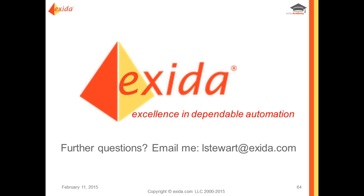Next, if you want to improve your PFD average, if you think back to the calculation, what were the main pieces of information in that calculation? You can decrease your proof test interval. You can decrease your mission time. You can change your architecture to 1 out of 2 or 2 out of 3, or you can revise your proof test coverage. A few of those will dramatically change your PFD average, but you can play around with different combinations to get to the PFD average that you need to be at.